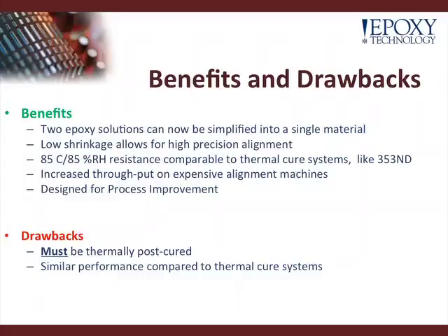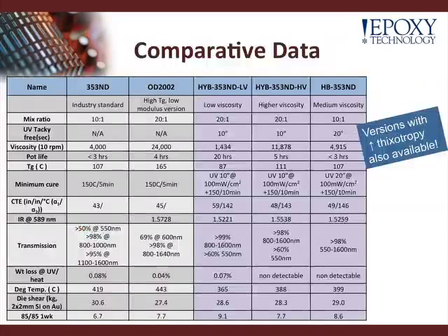The thermal post-cure is required. And for thermal post-cure, we're typically talking about minimum 80 Celsius, preferably up to about 150 Celsius. And again, they have similar performance compared to thermal cure systems. This is not necessarily a performance improvement, but a process improvement. Now on to the data.